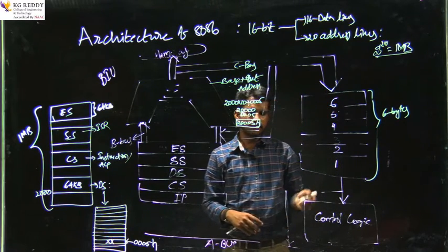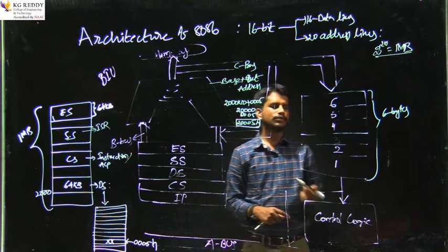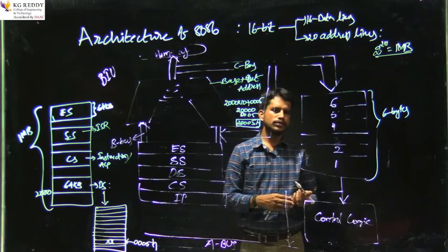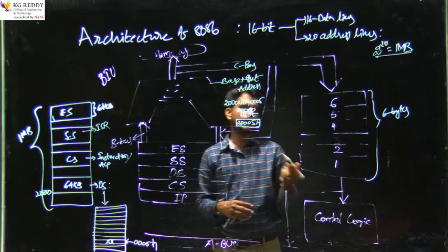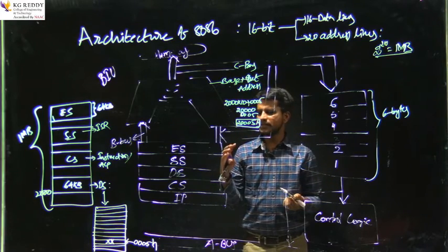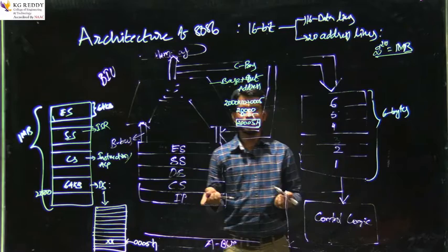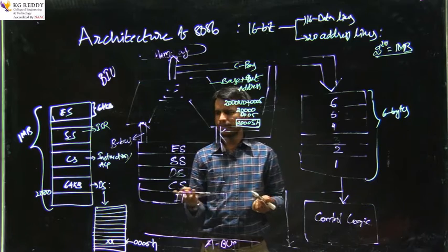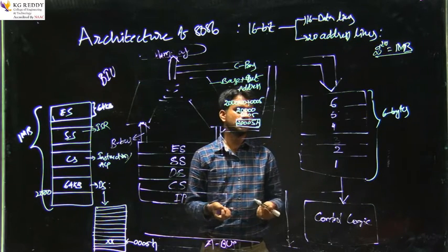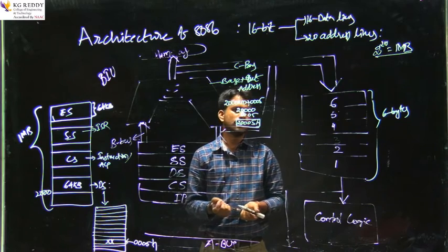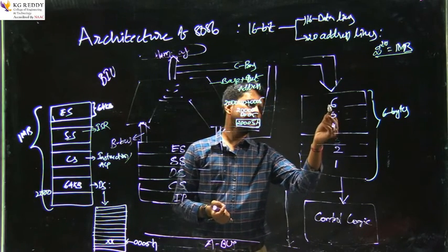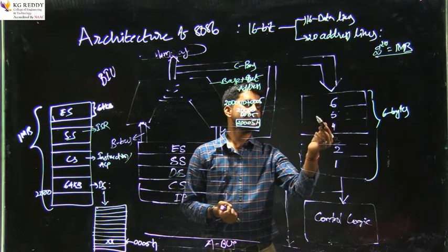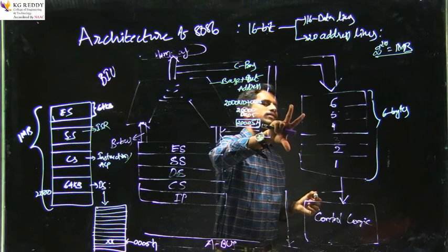As we know, the 8086 microprocessor has different kinds of instructions, like arithmetic, logical, control transfer, branching, loop instructions, etc. But the different instructions are of different size. One may be 1-byte size, 2-byte size, or maybe 6-byte or 4-byte size. It depends upon the type of instruction which we are going to use or define in the program. So at maximum it can store six instructions which are of 1-byte size, or it can store only one instruction of the maximum size of 6 bytes.